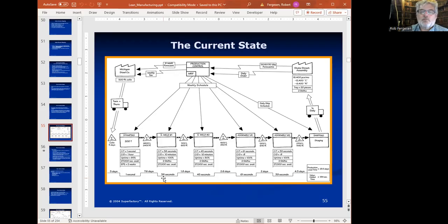It shows you product being delivered on the right side to a different assembly plant. So that's your customer in this particular product. So this map, this is a classic value stream map. It shows you how you're making that product, not in how it's assembled, but the steps required and how long each step takes to produce that product, and then where those inventories are in between those steps.